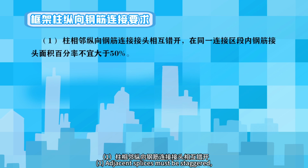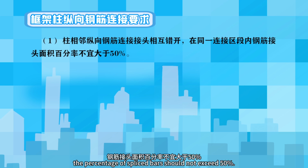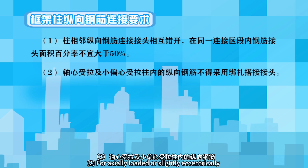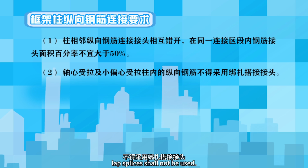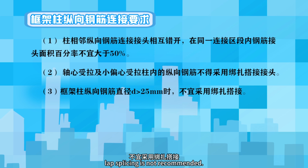1. Adjacent splices must be staggered, and within the same splicing region, the percentage of spliced bars should not exceed 50%. 2. For axially loaded or slightly eccentrically loaded columns under tension, lap splices shall not be used. 3. For longitudinal bars with a diameter greater than 25 mm, lap splicing is not recommended.